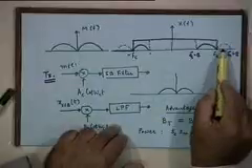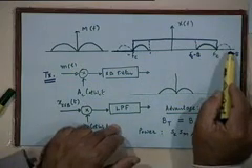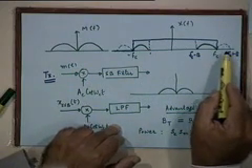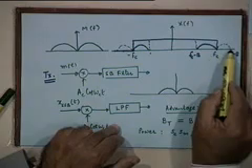I think the question is, can I use this bandwidth or not? Can I use this message bandwidth or not? Yes, of course I can. I can put another message in this bandwidth. When I discuss frequency division multiplexing with you later, we will see that this is precisely what you do. These are the advantages that you derive from SSB.